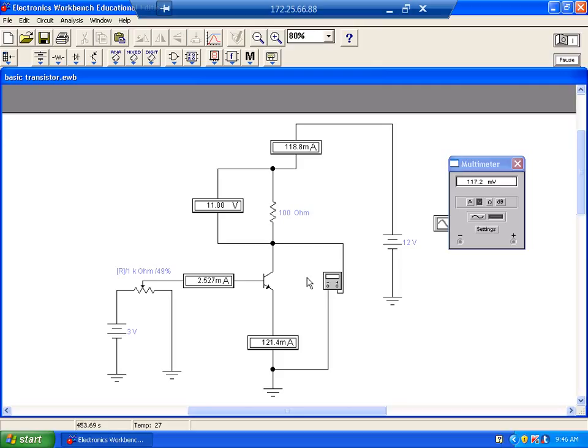Now it's still got current flow through it, right? When we operate it in cutoff, then you got to understand, if I've got enough voltage, I can push a current through anything. So we have a breakover voltage between the collector and the emitter. If you push current through that thing backwards, then it's going to burn it up.